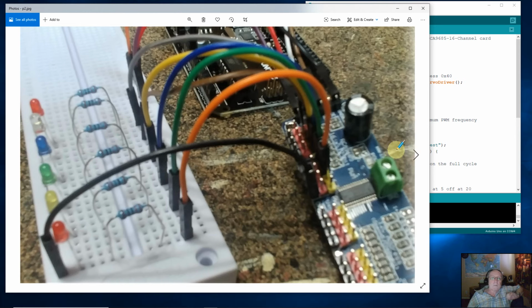Another shot from a different angle, but it's for a reason, of course. I want you to notice that on the module you have a row of yellow pins, a row of red pins, and a row of black pins, and they're important to us. If you connect sensors to it, or our servo motor or anything of that nature, they require 5 volts to run, and ground, of course, to return the power, and then they need a pulse width modulator to command it. So you have one of each of these in these rows here.